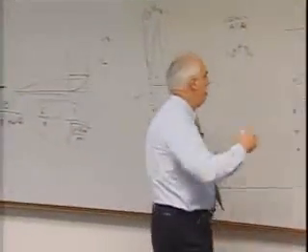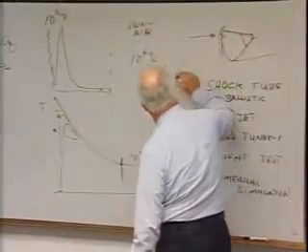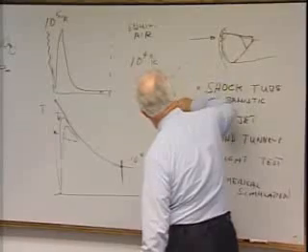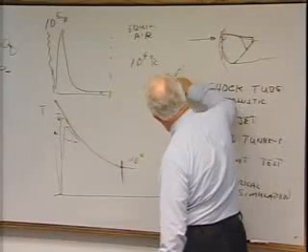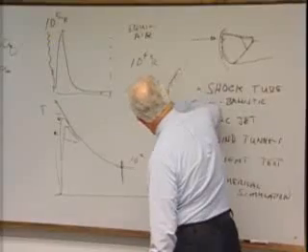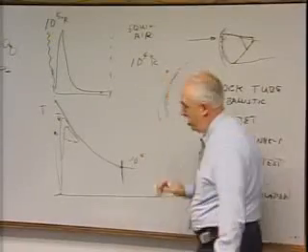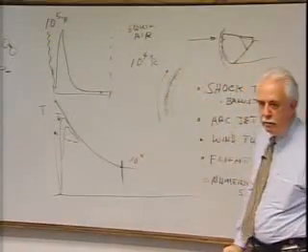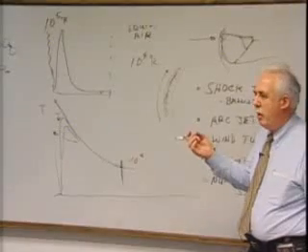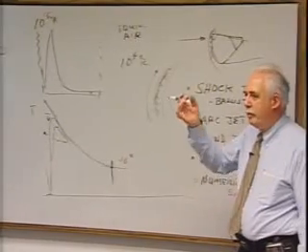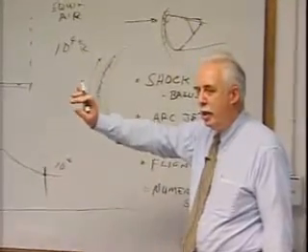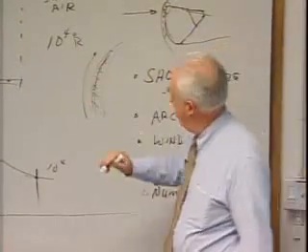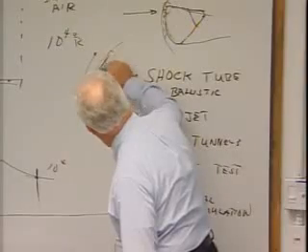If I blow that up a little bit, I've got a surface here of ablator, which is pyrolyzing and charring, and I've got a flow over the vehicle. I've got one heck of a pressure gradient. And I just described this char. It's a nice porous carbon like a charcoal briquette. You ever blow on a charcoal briquette? You can blow your air right through it, and it flames up. That's exactly what happened here. We had flow through.